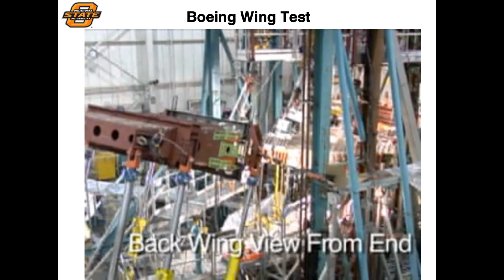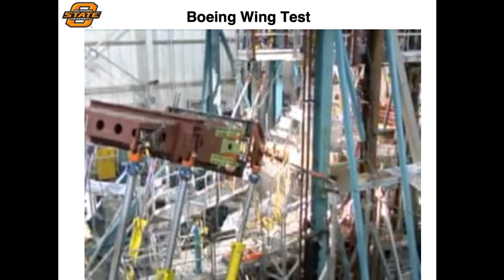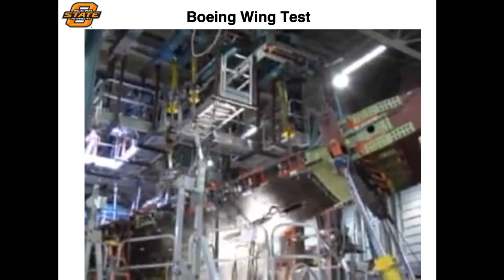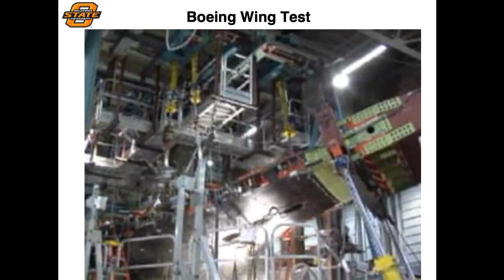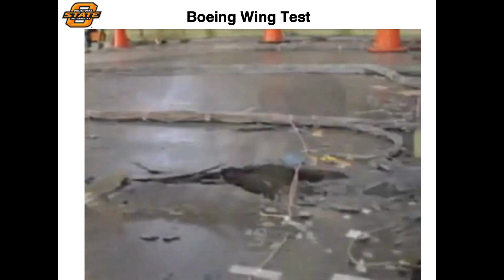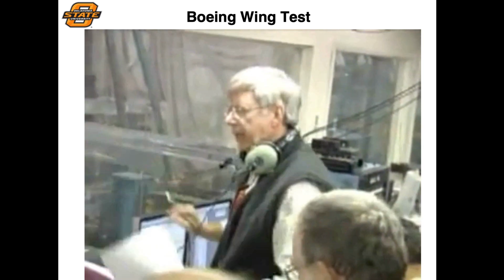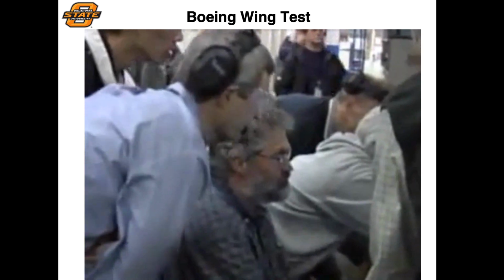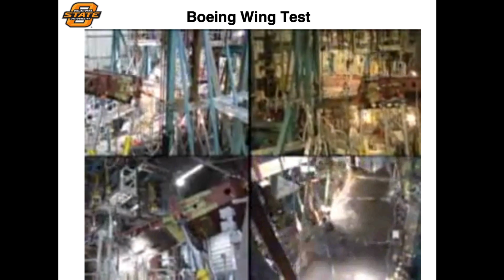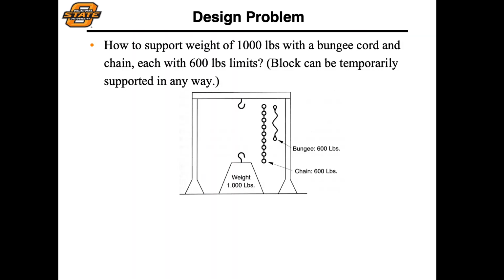And you'll see this snap here in just a second as it reaches over that 150% design point and essentially breaks. Keep in mind that this is a partial composite wing design, so it doesn't just necessarily snap off. There's a failure in it. There's a lot of energy now stored up in these wings, and you can see how it essentially breaks in two. They're all happy because it failed, but it failed where they expected it to fail, which is exactly what you want from a testing standpoint. You've already gone through the process of designing this and you know where it's going to fail, so you're validating your predictions.